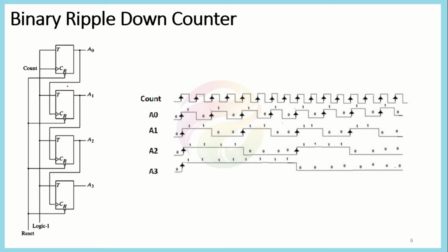The basic circuitry remains the same, just there is a slight difference here, because now each of the flip-flops involved in this circuit is triggered by the positive clock edge, not the negative clock edge. All the flip-flops involved in this system are triggered by the positive clock edge. So what we have done is that first we have represented the main clock signal of the system by representing the arrow at the positive clock cycle. Each of the arrows represents the positive clock cycle.